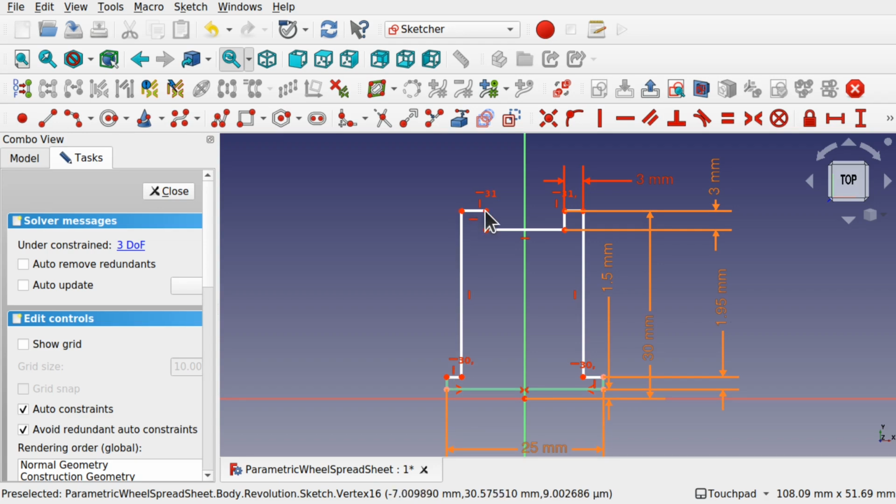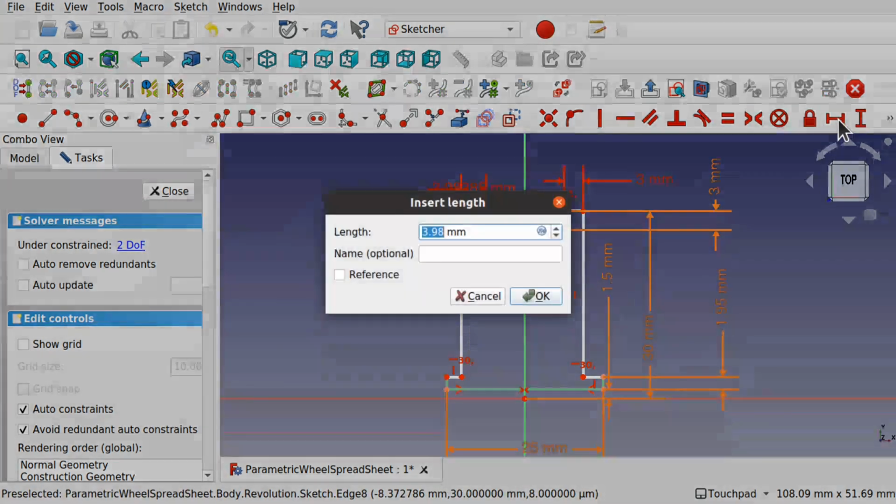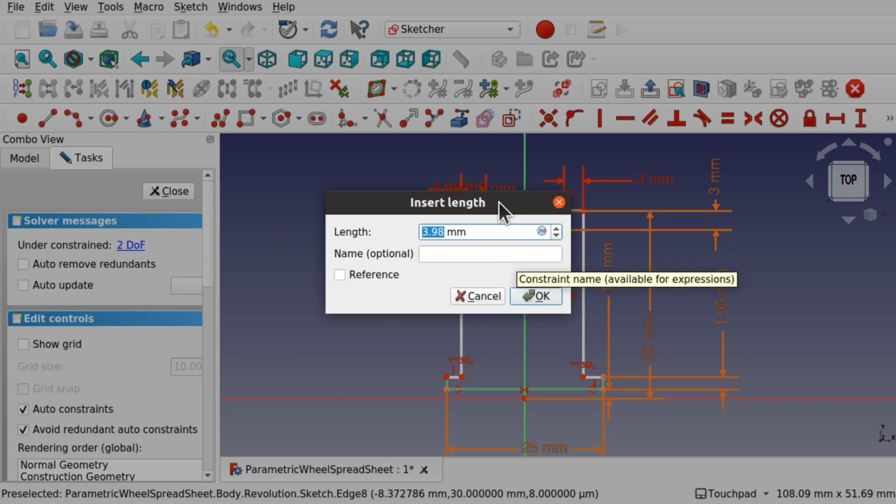Now we've got that one. We've got this one in line, so this one doesn't go up and down, but we've got some width to deal with here as well. Let's set these to be the same, because we can't use the equality because it gets damaged when we change it in our sketch.